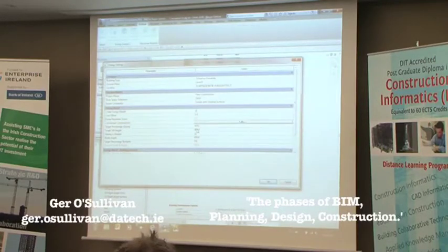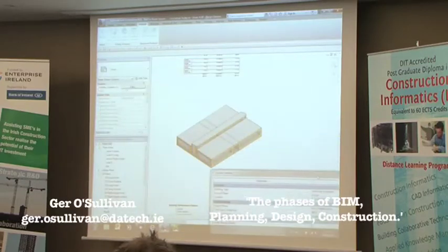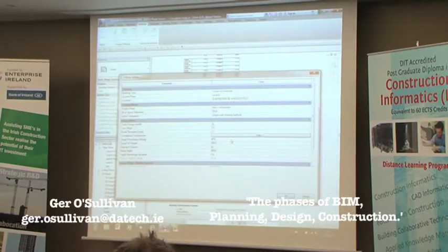We then can decide to put in a percentage of glazing. I don't even have to draw windows to create those opes. I just say I want 40% glazing on each room, and that's what it gives me back. Give it a sill height. Again, that's completely editable afterwards. I can change the actual openings, so I can get as close as possible to what the actual opening is going to be. And then we can put in skylights and all that if we needed to.